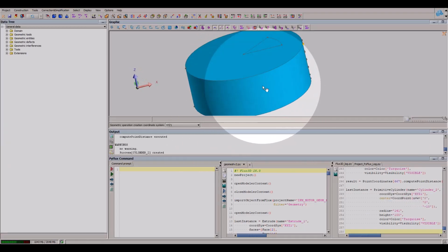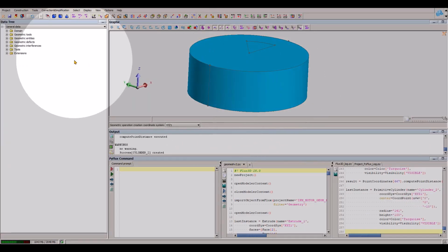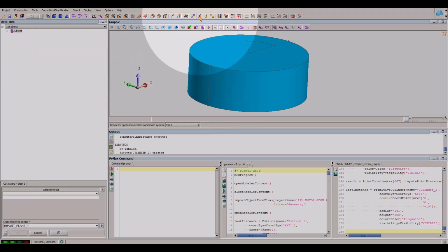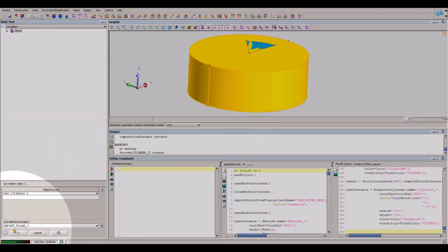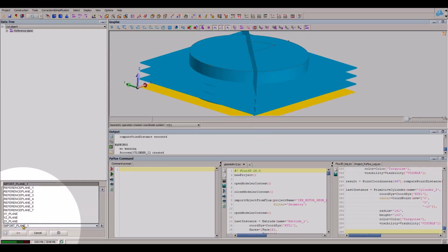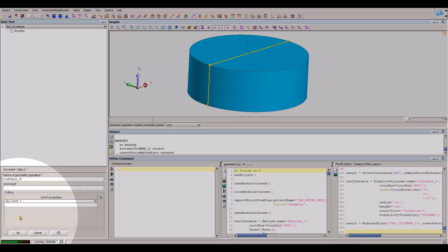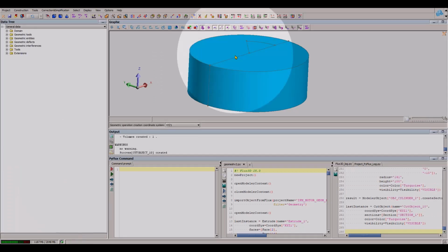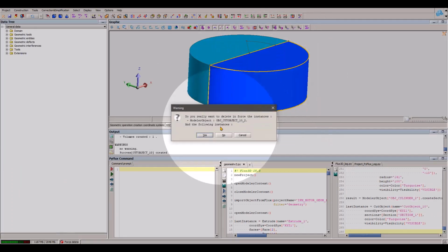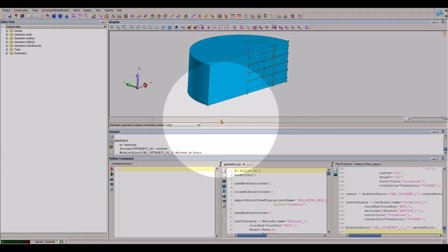So I create again a big cylinder surrounding all the rotor and the stator. I will cut the cylinder to have one portion, and then I will make later an assembly between this surrounding portion and the other parts of the stator and the rotor.